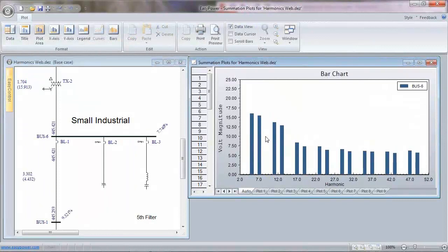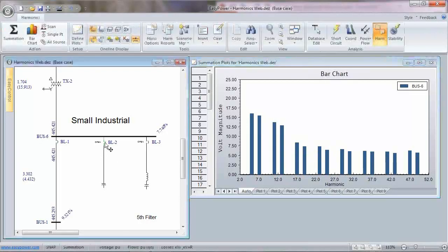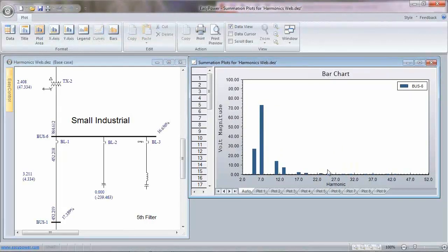Normally, look at it, it doesn't go down quite as much. The reason is that the reactance of the system is going up with frequency. So even though the current is going down, down, down, you reach a point where the voltage distortion continues almost linearly because of the increase in reactance of the system. If we have a resonance, we can see where the resonance is.